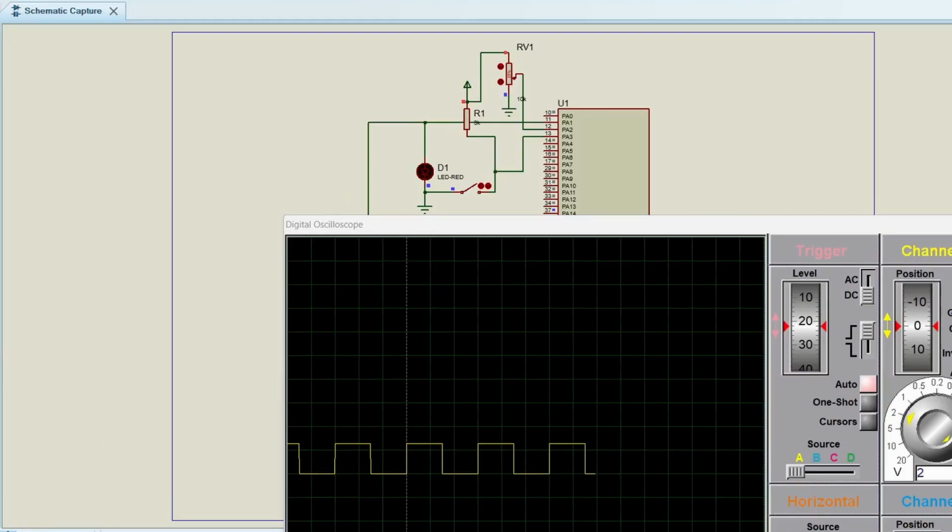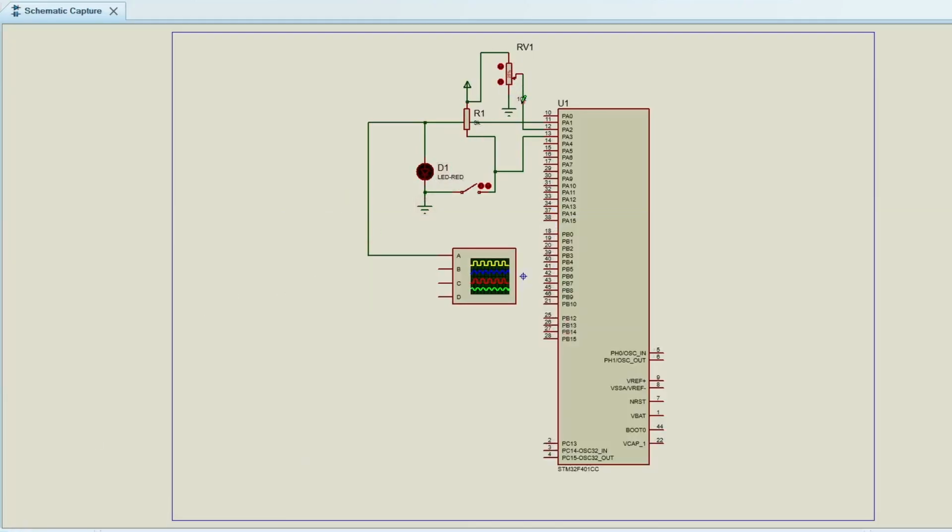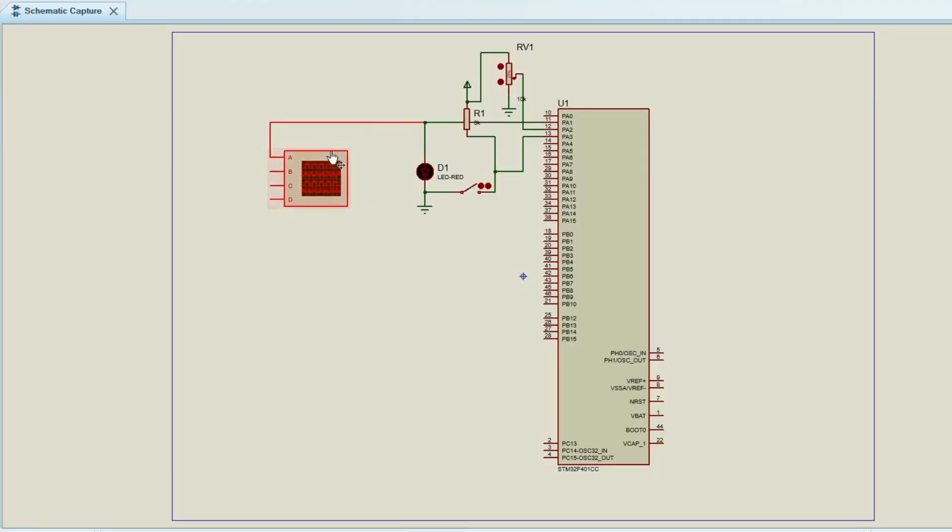Now what we will do is we will configure this port pin as an analog input. Whenever it reaches 75% of the maximum value, then we will start toggling of the LED, and whenever it reaches 25% of the value, we will stop the toggling effect of the LED. We can use both the logic, but for now for our testing we will bypass this, as we have not started with our UART where we can see the ADC values. That's why I am using this option.